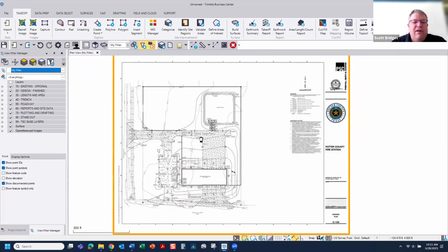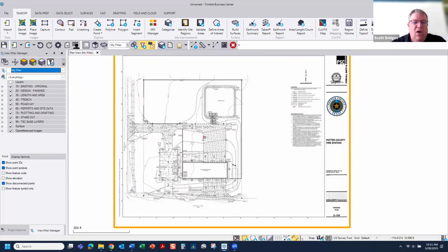Okay, what would we do at the very beginning if all we had was a raster PDF? Nothing that we can extract the data from, and we just have to do on-screen digitizing. Everything we should need is sitting right here under this takeoff menu. I'm just going to put in a few of the existing lines to let you see this workflow, and then we'll move ahead.